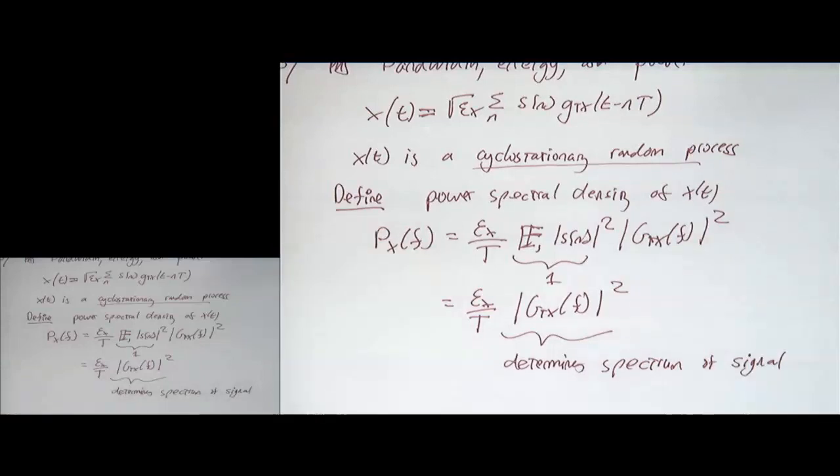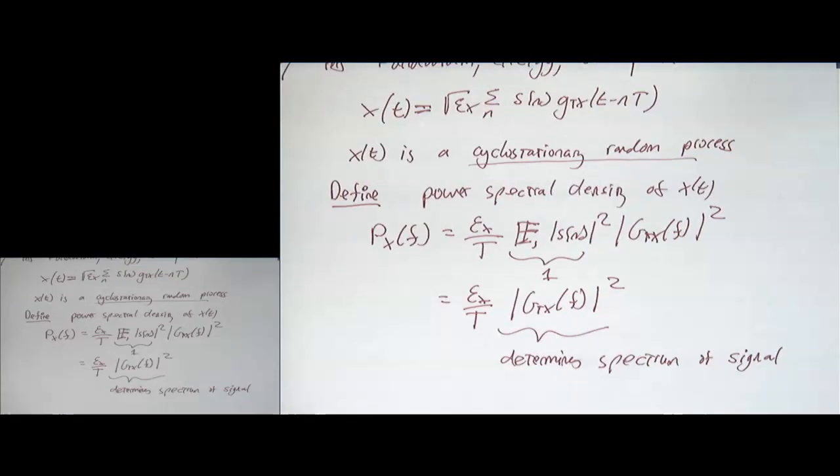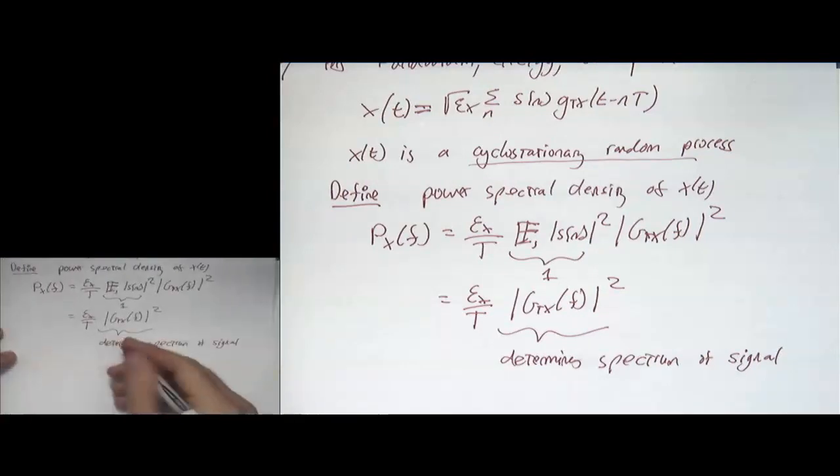Anybody remember the Fourier transform of a rectangle function? It's like a sinc. Not band limited by any stretch. So that would be bad. So we're actually going to use smooth pulse shapes, and we're going to derive, if we have time later today, some formulas that start to tell us what good pulse shapes look like. But if we want to make this band limited, we can't use the simple ones that we always think about, like a square wave. It won't work. Won't make it band limited. So if we want to make the signal band limited, we have to play with the pulse shape here. So that's the first major point here.